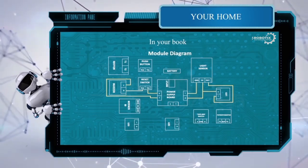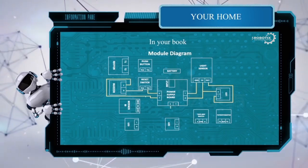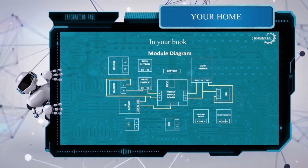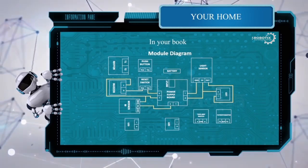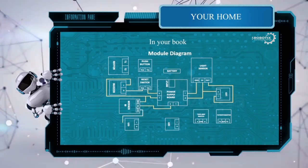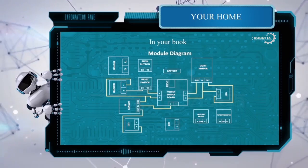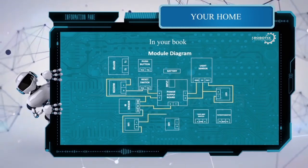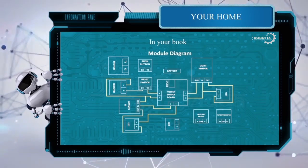So again, give the positive and negative to infrared sensors 5 volt and ground respectively, and the output will be connected to the positive of your LED, and the negative of your LED will be connected to the power supply board's negative. And then the next one is a switch in fan.